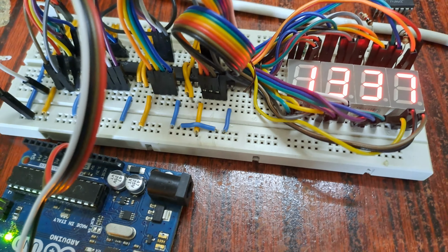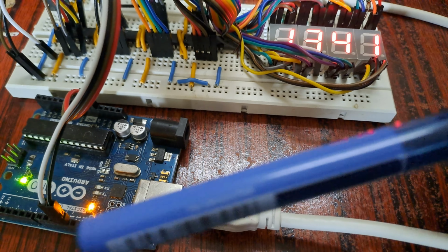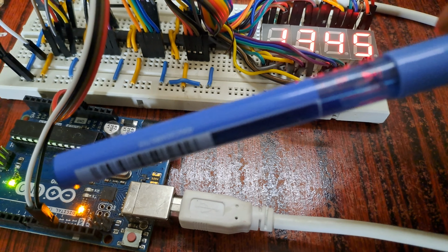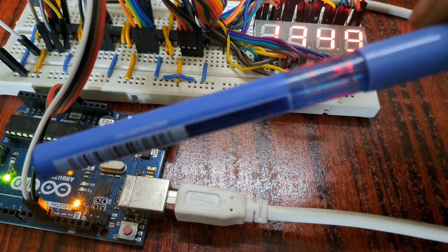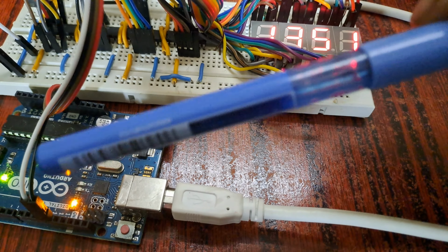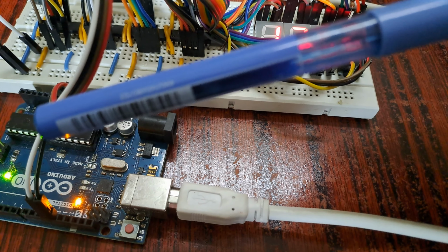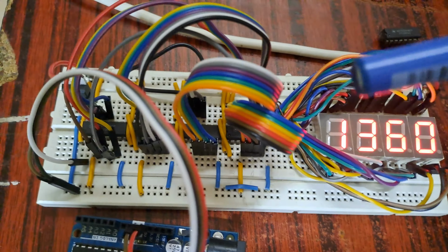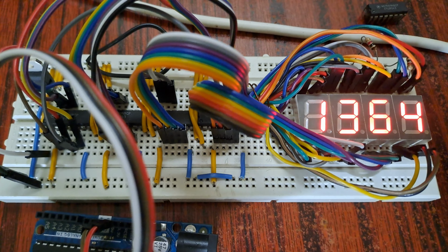Now you can see here I am using a serial in parallel out combination with the Arduino Uno. Arduino Uno is sending one serial data and another clock data. The white wire is the serial data wire and the black wire is the serial clock wire. Okay, so data is traveling from the white wire and the clock is traveling from the black wire.